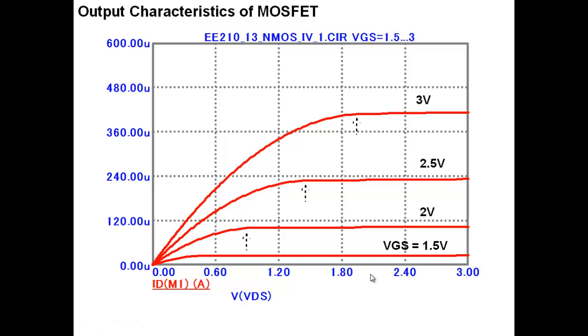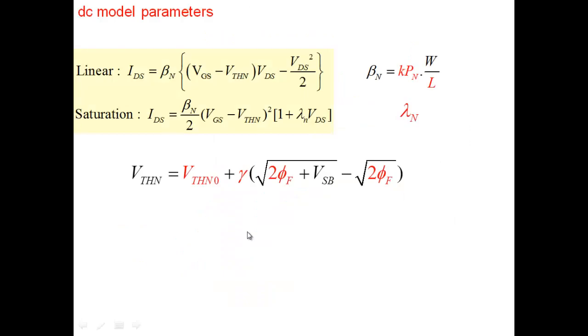So we call it the transfer characteristics. These are the points where drain saturation occurs. Note that saturation occurs at different points here. VDsat is equal to VGS minus VTN. So 3 minus VTN is 2, so saturation occurs at 2 here. It occurs at 1.5 here and at 8.5 here.